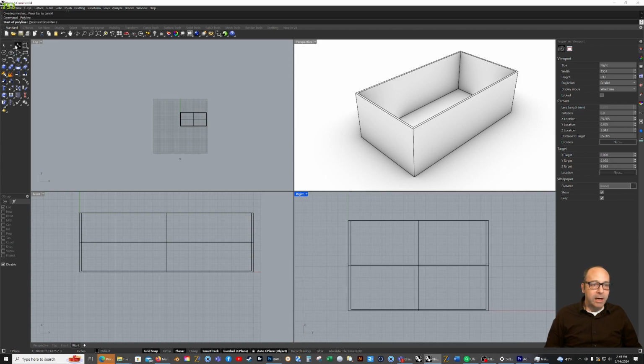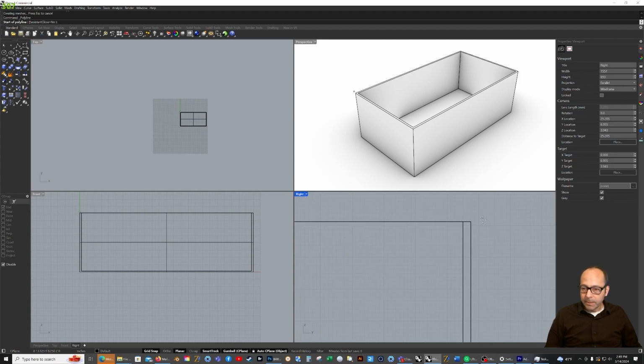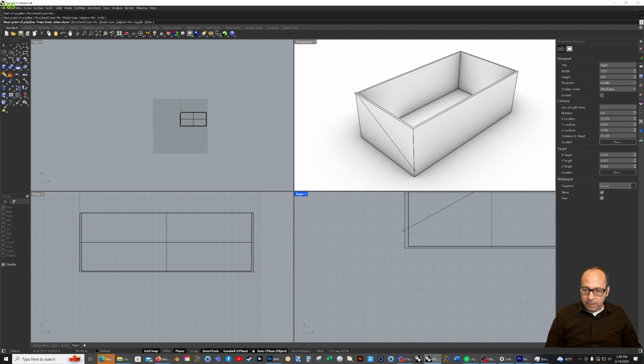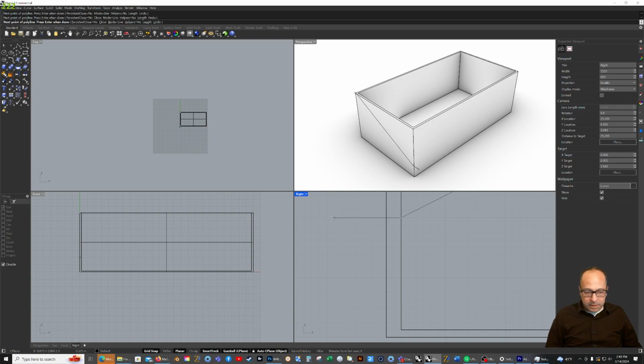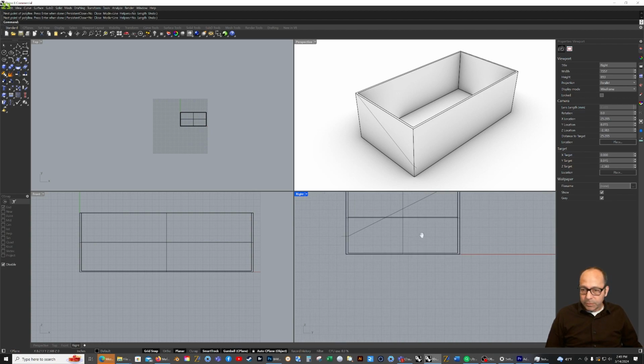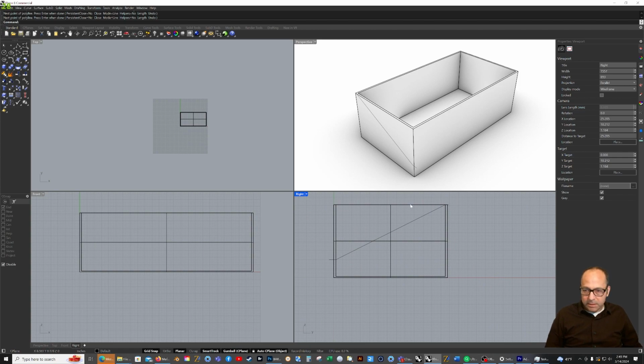So I'm going up to the polyline tool up here. Same settings with the grid snap. Click here. Want a 2-inch lip on here. And I know the major grid lines are inches, so it's 1, 2. And I'm extruding past. I don't know if you have to, but that way you know it's going to be able to cut. Now there's 2 ways I know to do this.